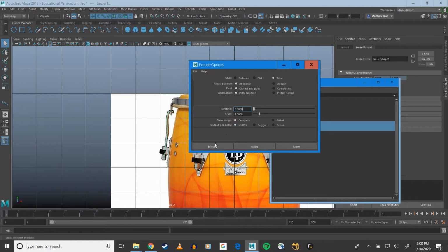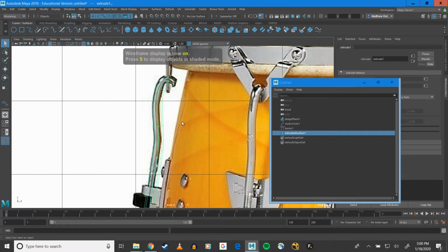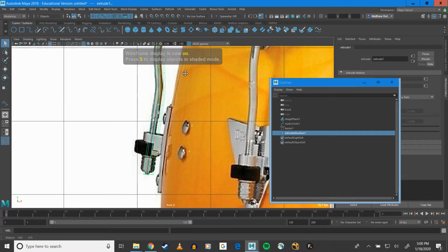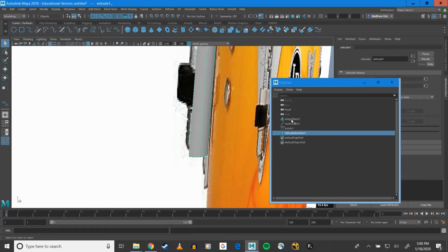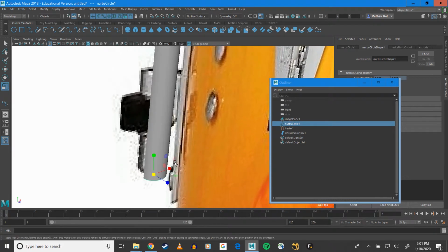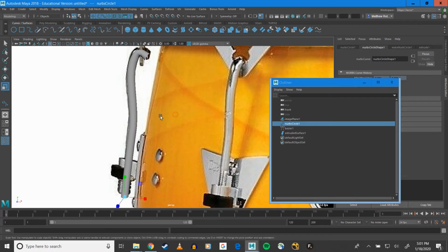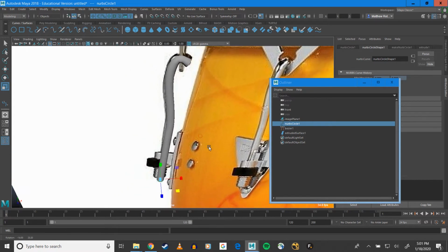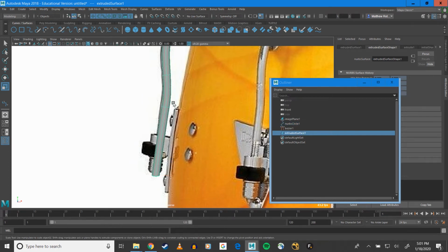I'll just hit extrude, and I get something that will match what I'm working with here. Now, I should even be able to get my original Nurbs circle, and I can scale that in or out after the fact, even. And then I can get this.